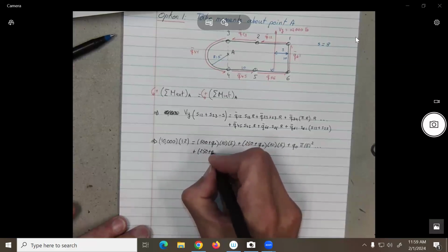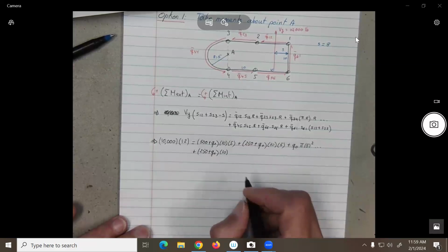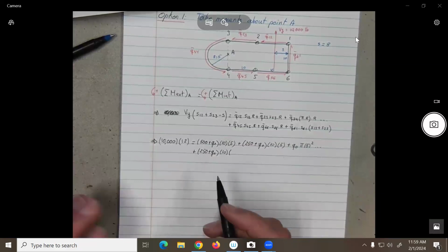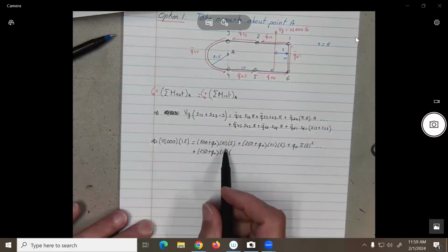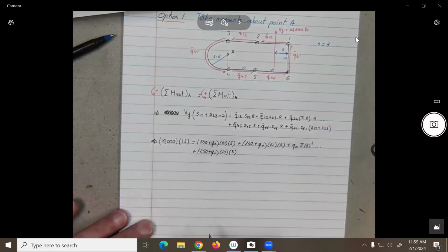So this is now where you make the mistake. Times 10. Now what is R? That's a mistake. If you put negative 5, then you reverse the sign of the moment, no? Remember, these are distances, no? So you need to keep over here the 5. It's not negative 5. We're already taking care of the sign in the moment equation.